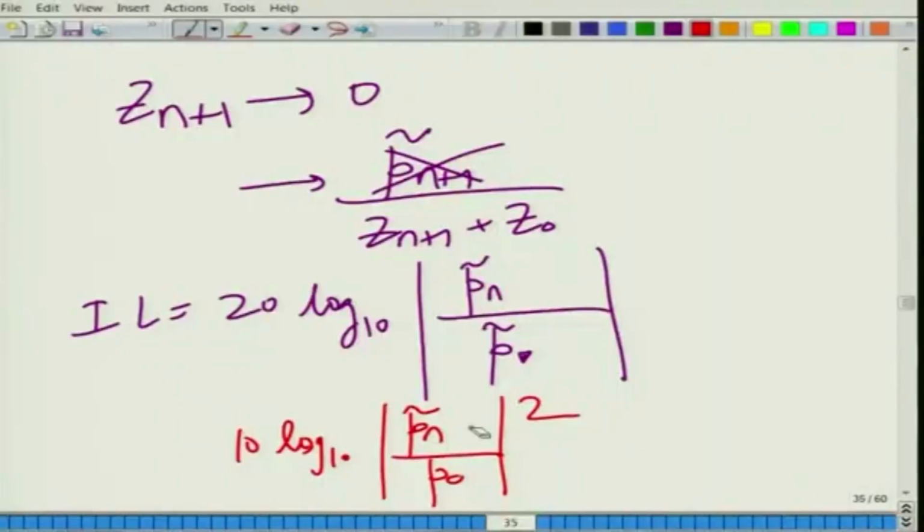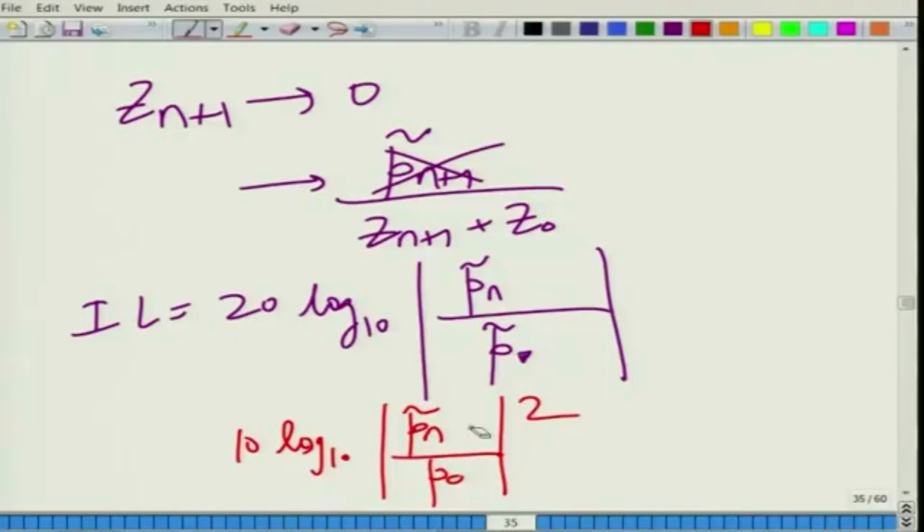For insertion loss we just need to measure the pressure without the muffler on at a given location, put the muffler on and measure the pressure again at that point, and then take the ratio. For a constant pressure source, we can experimentally get the insertion loss, measured in dB or dBA.